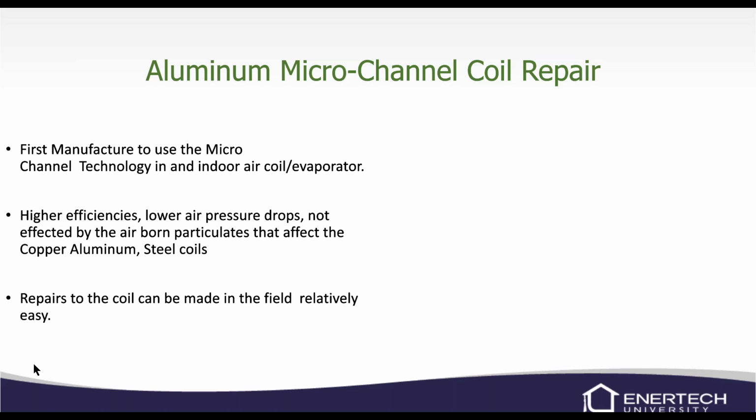If you have a problem and you need to repair that coil, there is a kit we can get you, and we'll get you the video at that point too. Because if you feel comfortable brazing on aluminum, go right ahead. But this is more of a last resort thing that I would do. So I just like to mention that we do have a coil repair kit that you can get.